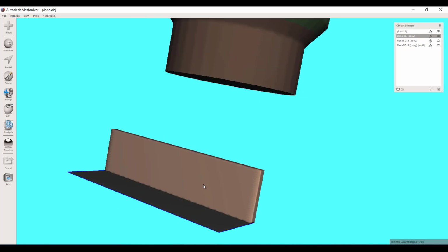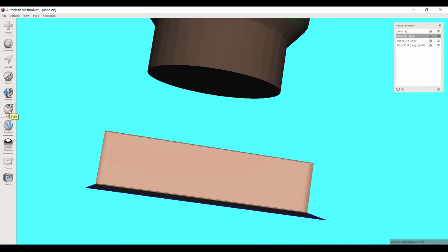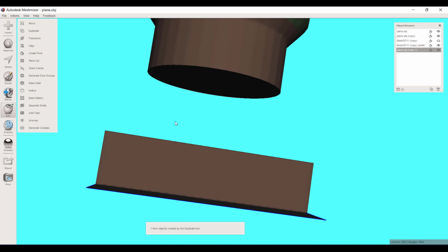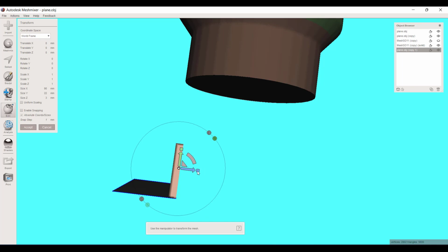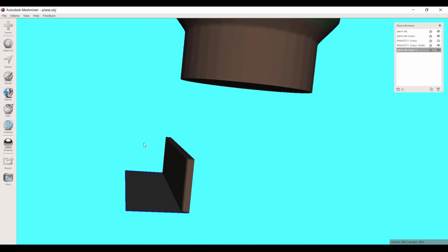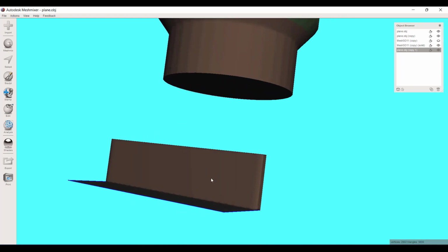The way I'm going to do that is, first of all, let's duplicate this shape, edit, duplicate, and I want to add 4 millimeters this way and 4 millimeters this way. So that duplicate, let's hit transform. Currently the width in the Z dimension is 3 millimeters. So what if I added 4 millimeters to either side? That would make this 11 millimeters. Oh, okay. So right there, it wants to jump off just in a single direction. So let's actually backtrack on that.